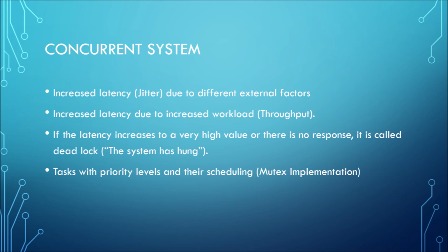Tasks can have priorities. A higher one can interrupt and pause another. In the imaginary example of the voltage source, the task that measures the current has the highest priority, and in case of an overcurrent, it should not only pause the others, but also stop them, open the protection relay and inform the user of the problem on the display. The assignment of priorities and the control of them is called the mutual exclusion algorithm.